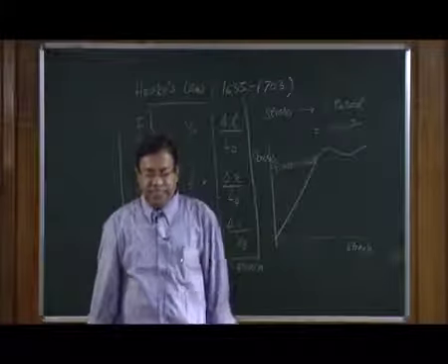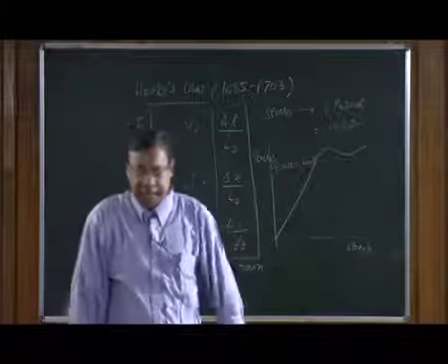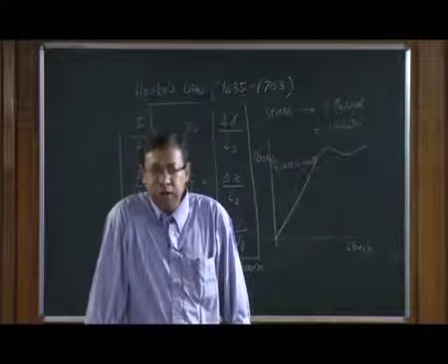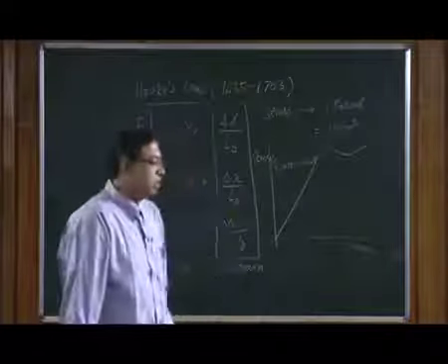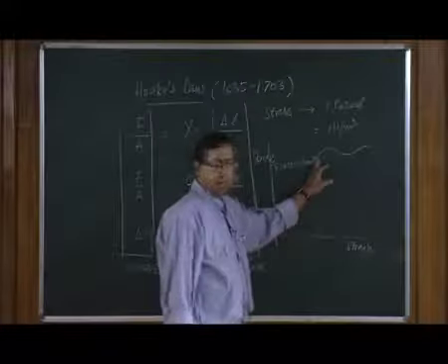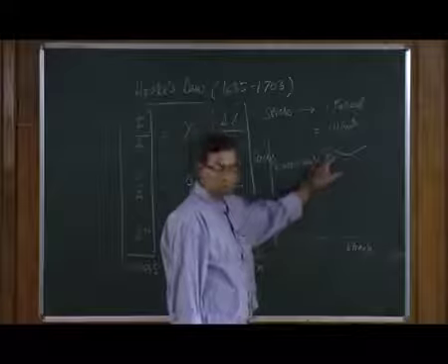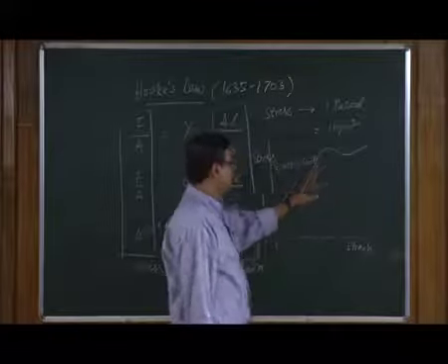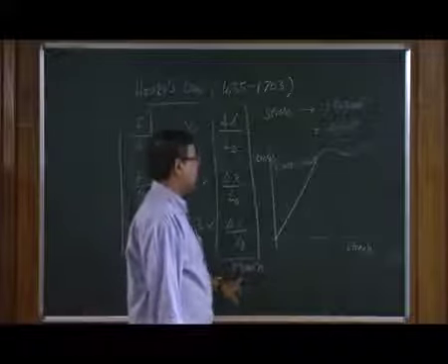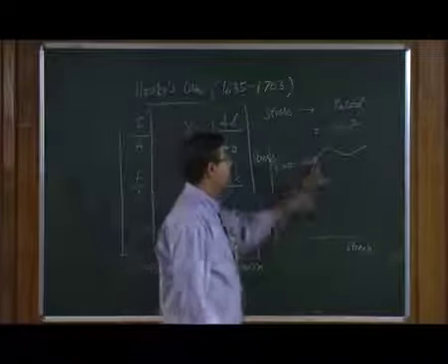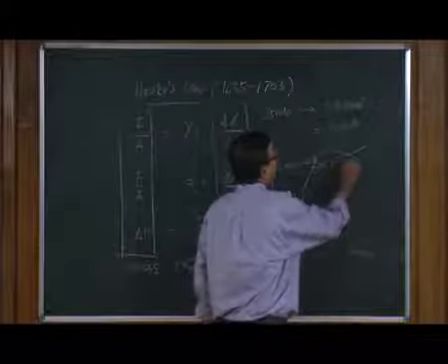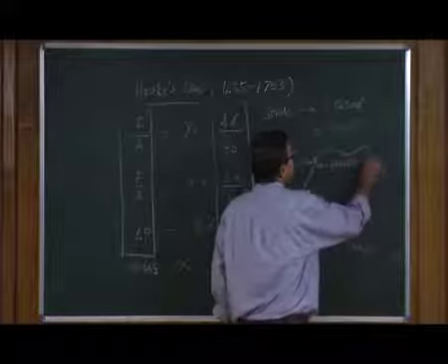The significance of elastic limit is that the body will regain its original configuration once the force is removed, and beyond this the body is not going to regain its original configuration, because stress is no longer proportional to strain, and you will have a deformation which is usually referred to as plastic deformation.